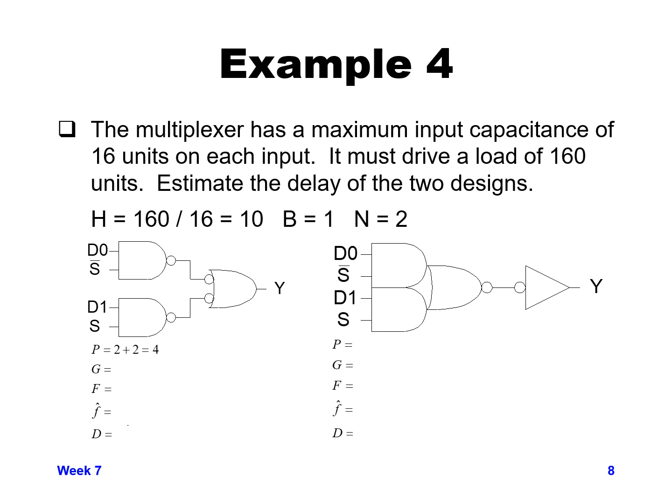Now for the path logical effort, we take the logical effort per stage and multiply them together. If you go back to the table that was presented, a NAND gate has a logical effort of 4/3, so the path logical effort takes each stage and multiplies them together. 4/3 times 4/3 is 16/9.